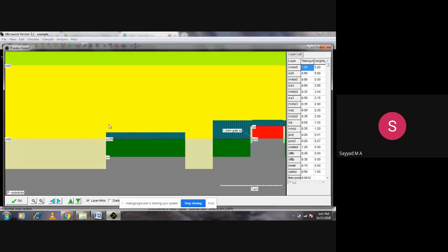Now you can see what happens. Actually, it is showing the next part also. Okay, I don't want to see this particular part. If you see this cross section for this much part, you will directly see the N plus diffusion, and this gray color is a P substrate, and above this are the different layers which are available. Okay, and here a violet color thin layer you are going to see. I don't know if it is visible to you or not. That thin layer, between this yellow part and this white part, is a thin layer of SiO2, and above that SiO2, there is something different.